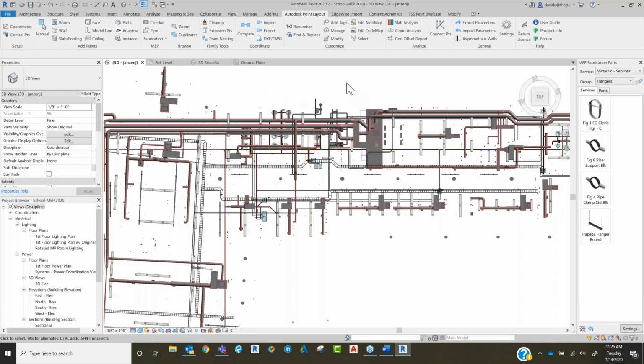Great. So another one of the questions that was asked was, what about stake data from the field to review for tolerances, verify accuracy, placement, et cetera. So you kind of went over this a little bit when you talked about import, but the workflow is you can send this data out to the field. They'll lay out. There might be things that they're capturing while they're out there that aren't in your model as well. You can re-import that information, as David was showing with the scan.